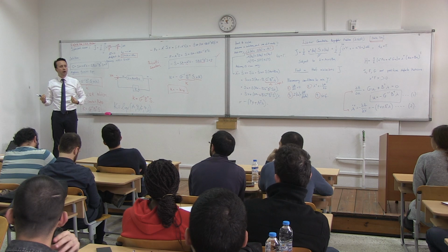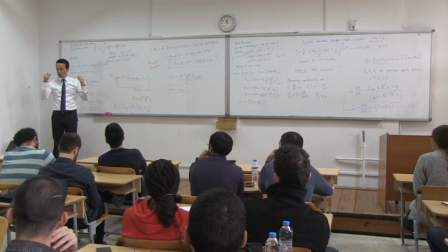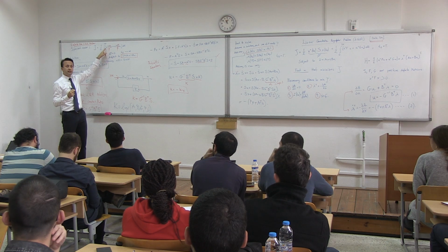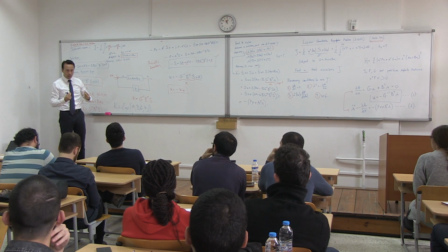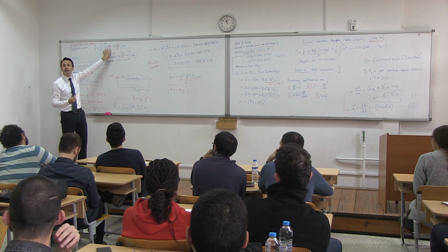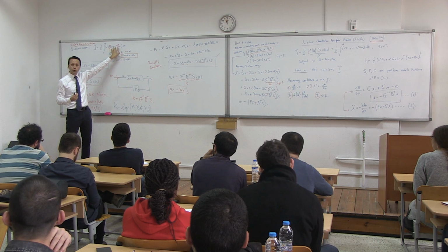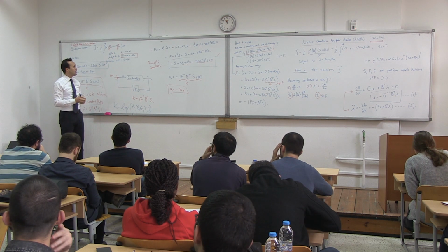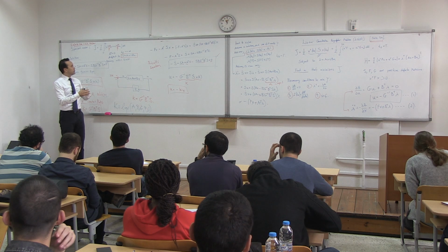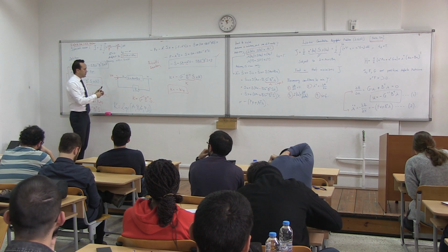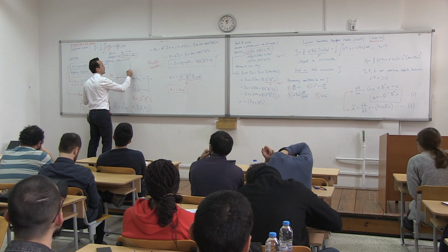And J is a number. It's not a vector, it's not a matrix, it's a number, right? You multiply a vector with a matrix and a vector, you get a number, right? And it's called a quadratic regulator because it's like taking the squares of x's and taking the squares of u and multiplying it with a number, all right? So you're trying to minimize J. So let's think of this like that.